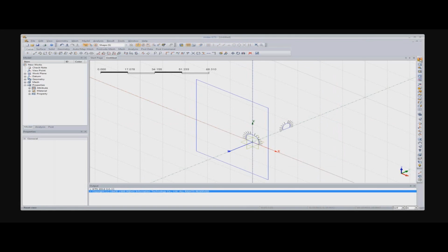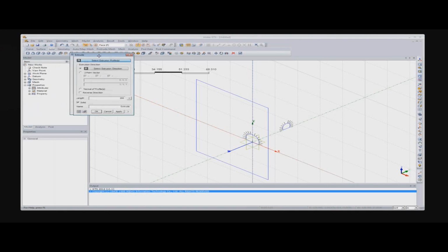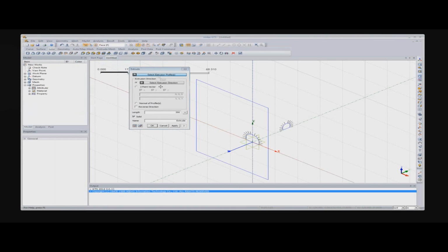So let's switch to this view, then we can see how we are extruding those. Okay. Going to the solid and then selecting extrude. Select the extrude profile, and then from here we go with the wires, this wire, and I want it to be extruded in the, let's select the direction first, and then 60 meter.